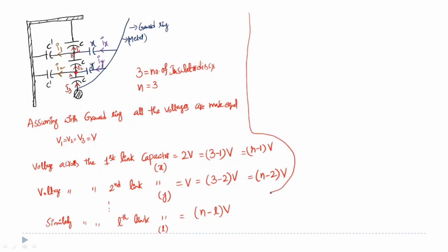Now, when these voltages are equal, practically by using a guard ring at node B, if you apply KCL at node B, what is the incoming current from this capacitor?